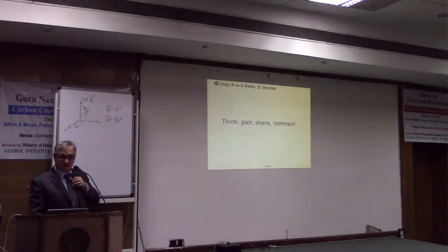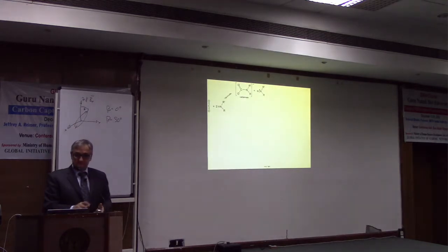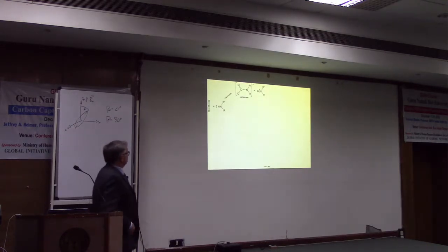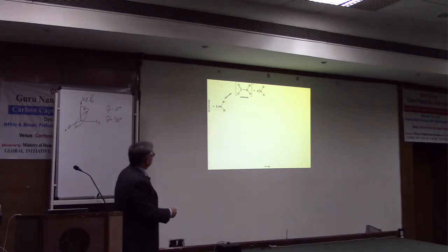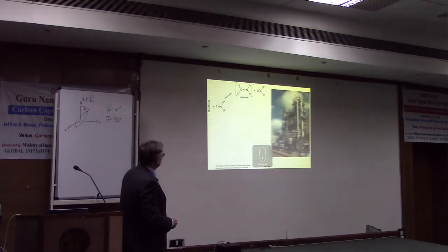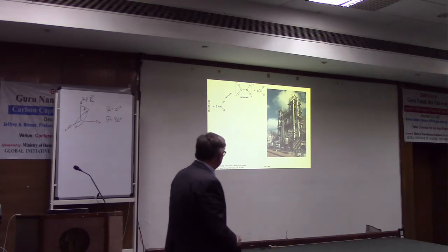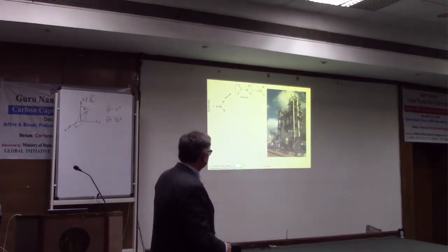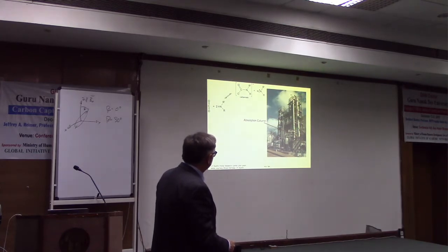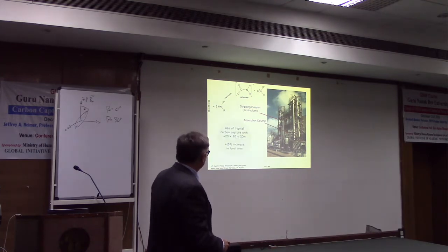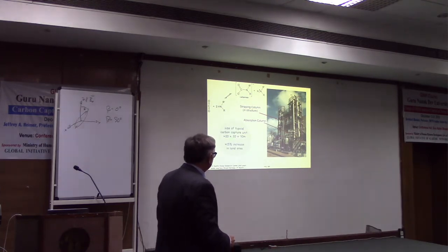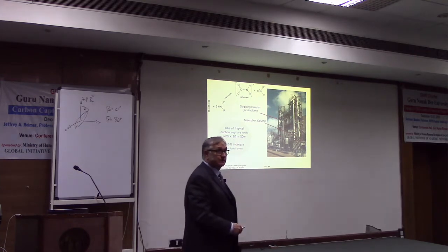So let's return to our... so the formation of carbamates turns out to be a critical part of all these amine processes. And if you examine what does that look like on a power plant. So here is a pilot plant from my colleagues at the University of Texas at Austin. This represents the absorption column right here. And over here, hidden behind the framework, is the stripping column. And the typical size of a unit like this is on the order of 20 by 20 by 20 meters.